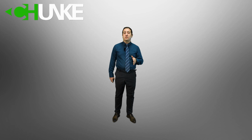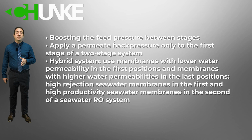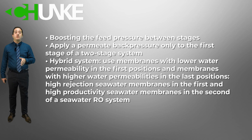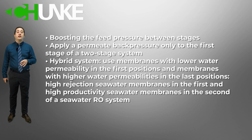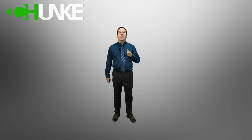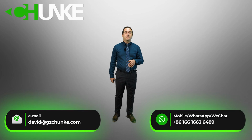The goal of a good design is to balance the flow rate of the elements in different positions. This can be achieved by the following means: boosting the feed pressure between stages; applying a permeate back pressure only to the first stage of a 2-stage system; or a hybrid system, using a membrane with lower water permeability in the first position and membranes with higher water permeability in the last position. Example: high rejection seawater membranes in the first and high productivity seawater membranes in the second stage of a seawater reverse osmosis system.